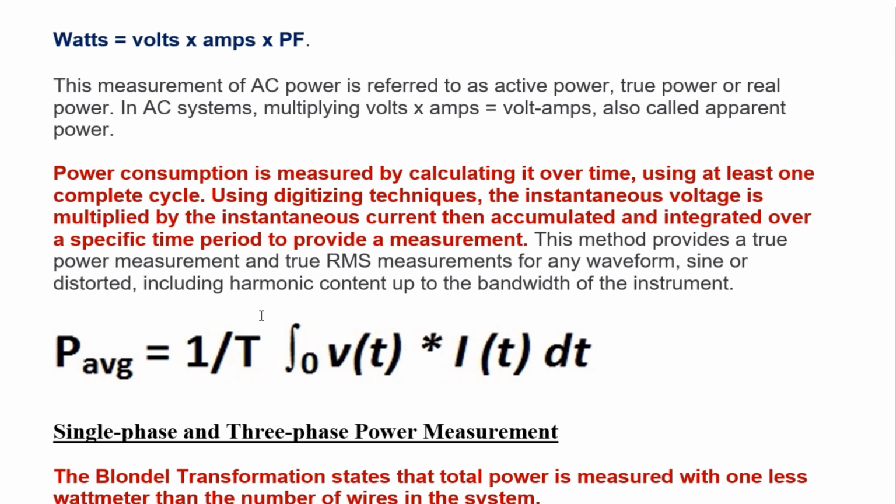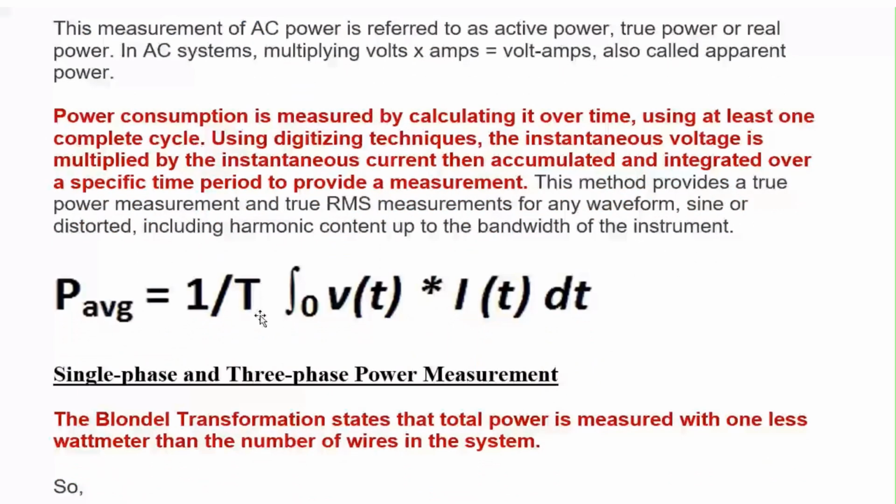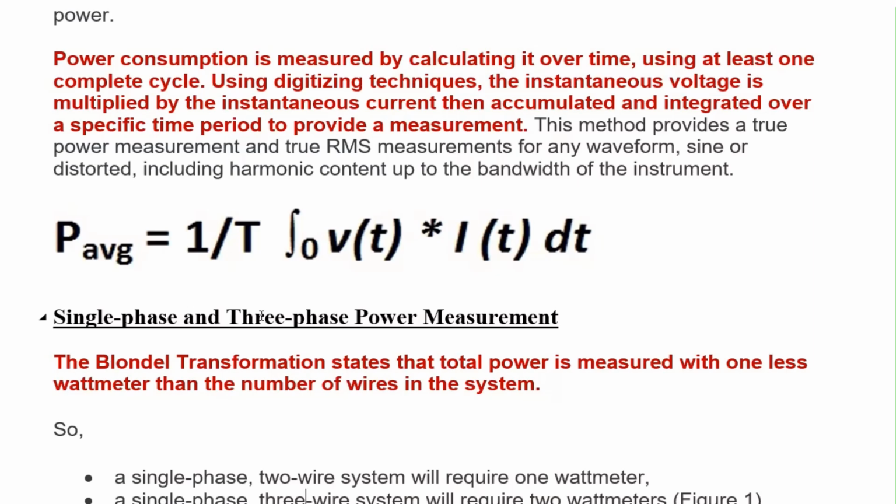It takes the sample of voltage, it takes the sample of current, and measures the phase difference between voltage and the current, and thus measures the power factor, and thereby gets the multiplication of all these three. That means V into I into cos phi, and predicts the power and measures the true power or power consumption in the circuit.